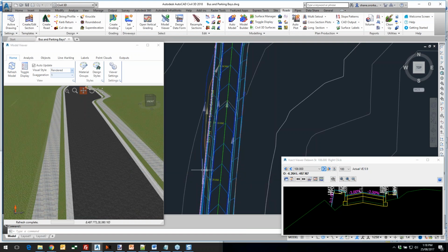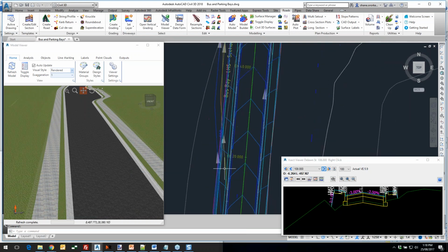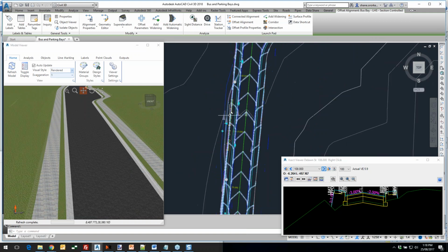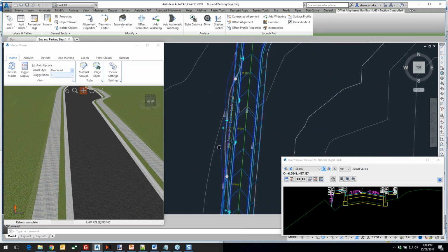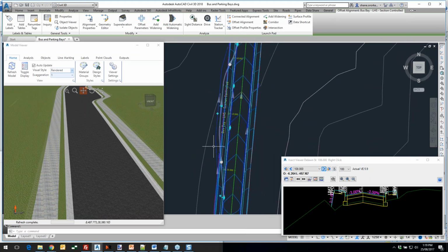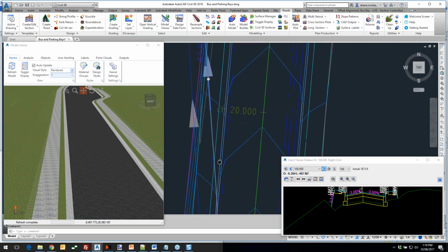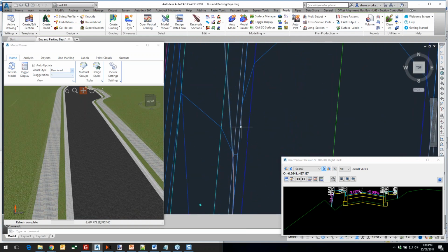Right, so what I'm going to do is change the template in the zone of where this bus bay is. Now, in terms of getting things exactly right, if we think about the sampling, wherever you sample a cross-section is where you can execute a change. So I'm going to be introducing addition here. I can see that there's a 300mm offset at this location.